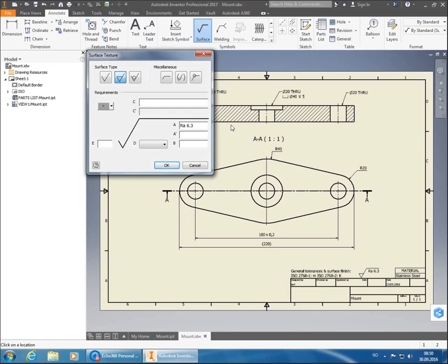Unless, for an example, you're creating something where you need a sealing surface, like inside a hydraulic piston or something like that, where you need an extra fine surface where you're going to seal it. Then you will need something finer than this. 3.2 is a good example of something nicer. Usually, you will then be working from a product catalog from a manufacturer of seals, and they are going to specify what surface finish you need. But often it's 3.2, especially for O-rings and stuff like that.